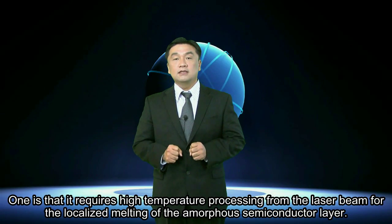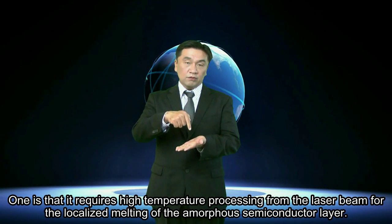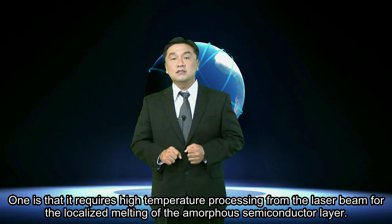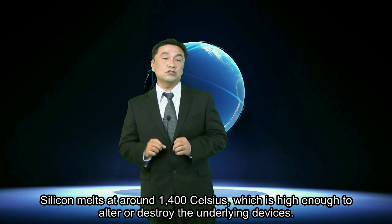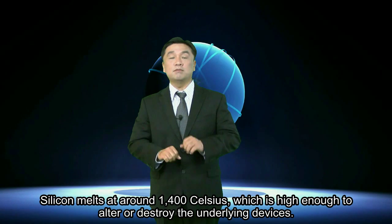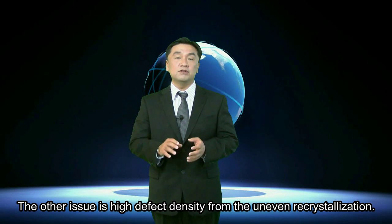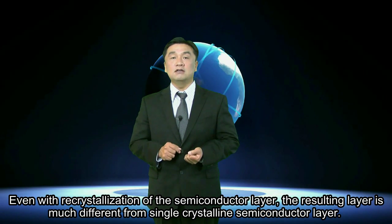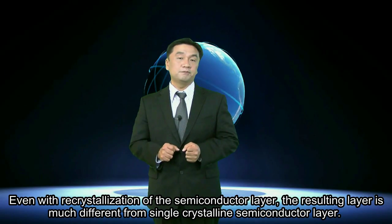The first is that it requires high temperature processing from the laser beam for the localized melting of the amorphous semiconductor layer. Silicon melts at around 1400 Celsius, which is high enough to alter or destroy the underlying devices. The other issue is high defect density from the uneven recrystallization. Even with recrystallization of the semiconductor layer, the resulting layer is much different from a single crystalline semiconductor layer.